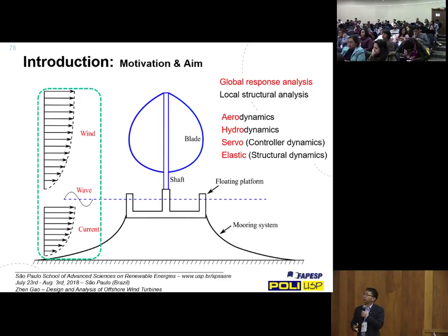And it's not easy to control the blade pitch angle for vertical axis wind turbines, especially for this Darrieus turbine. So typically you have a fixed pitch angle. If you have a straight H-type blade rotor, then it's possible to adjust the blade pitch angle as it rotates. So the idea is to look at the loads and the responses and then compare with the horizontal axis turbines.